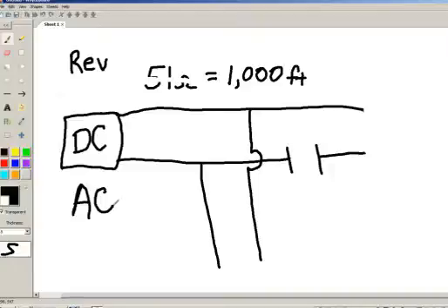My point is, any AC signal will go any place there's cable for it to go, right? So it goes down this way. It most certainly also goes down this way, right? Because that's why we knew our measurement would be inaccurate with the bridge tap in front of our open.